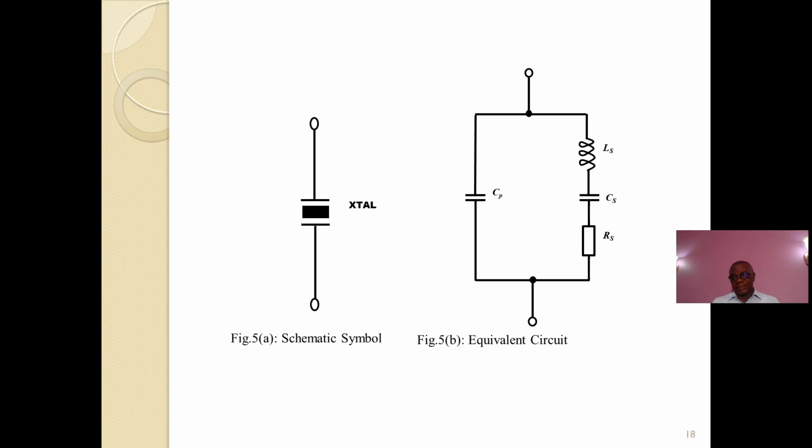It's a feedback lead-lag circuit. If you look at Fig B, you see that it is a parallel circuit. In one arm, you have the series RLC. In the other arm, you have the capacitor circuit, which is equivalent to RC because their internal resistance, even though not represented, is always there.